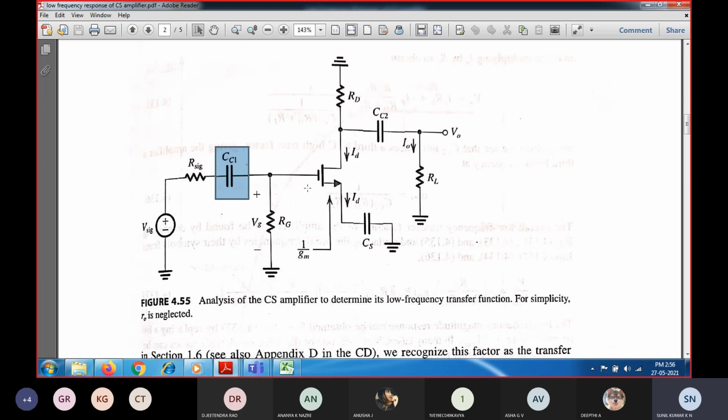So when we discuss the common source amplifier for discrete circuit, we are going to have these external coupling capacitors which have a very large value compared to the internal MOSFET capacitors, in the microfarad range. These external coupling capacitors couple the input voltage signal to the input side. At the same time, the output voltage across the drain terminal will be coupled to the output load resistance.